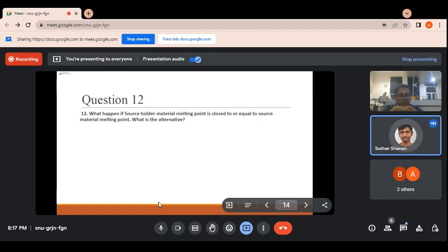Okay. So I also have a doubt. What is annealing in SU8? Why do we use annealing? Because we are using the soft bake and hard bake, then why do we again go for annealing? Annealing is a temperature treatment. If we want to remove the defects, then we give some temperature so the defects become fewer.